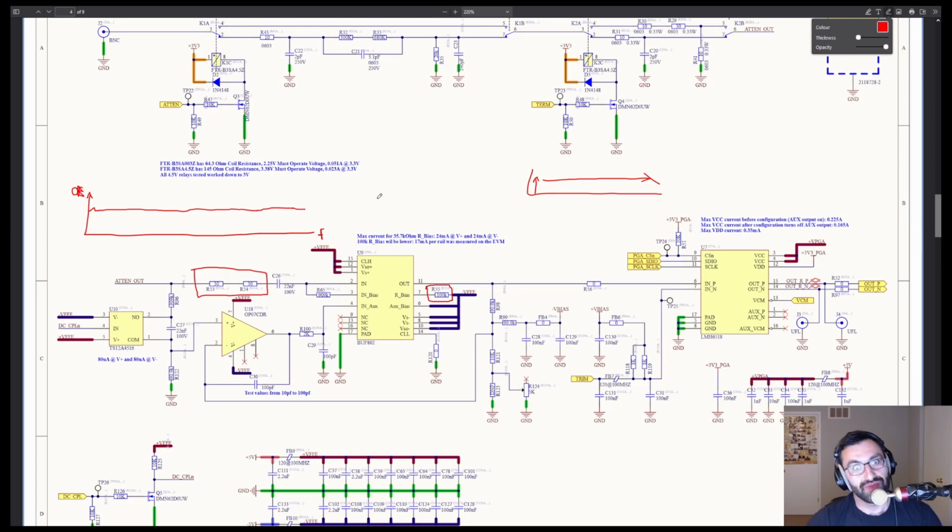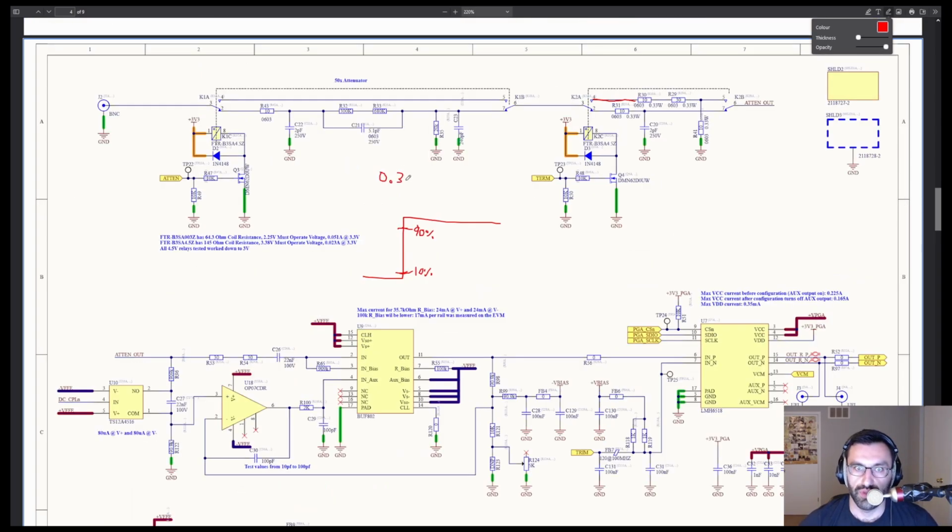The other way of doing it is by looking at the rise time of a very sharp pulse, right? So that rise time from 10 to 90% relates to bandwidth. There's a rule of thumb factor there of 0.35 over the rise time, and that gives you bandwidth.